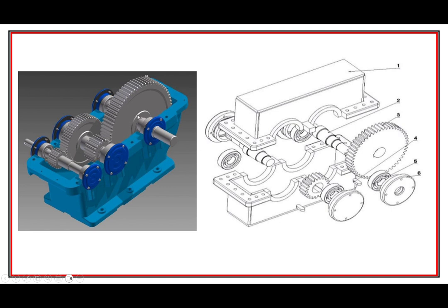It would fit into a gearbox that looks something like this, or a rendering of one at least. And we're going to do a step shaft. I'm going to highlight the intermediate shaft. So we have an input, probably over on this side, with something like a motor running into it. We go to this gear, and this gear is going to be high speed. This one's going to be slower because this is a smaller gear to a larger gear. And then this shaft right here is going to transmit that power over to this other smaller gear, which is also going to do another step down to make it even slower, and then this would be the output where we would put a load.